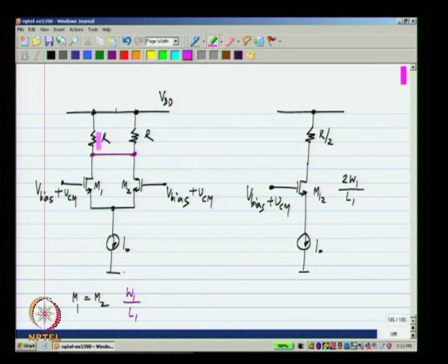Now, as you can see, where we had pairs of components, we have a single component for the resistor and the MOS transistor, and the component along the center line of the circuit, in this case the current source, will remain as it is. Okay. So, roughly speaking, the number of components gets divided by half. Okay. Whatever is in pairs will be half, and whatever is along the center line will remain as it is.